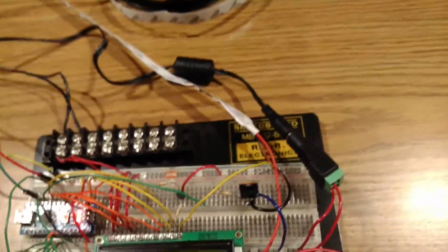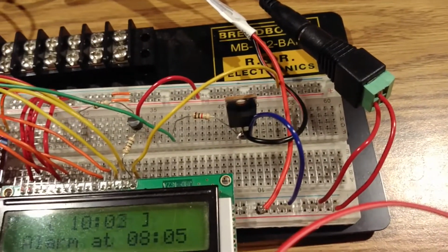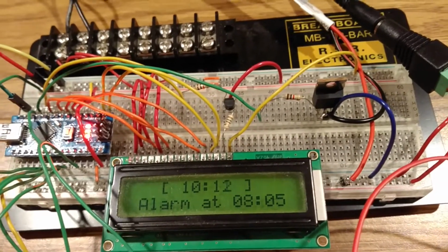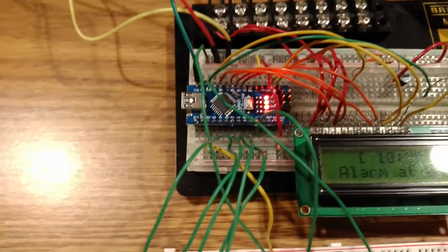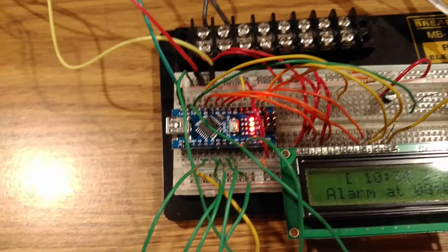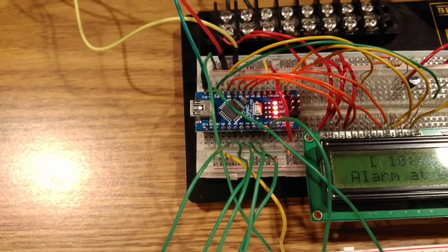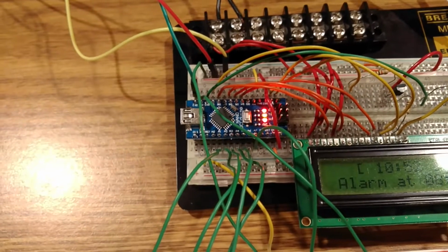For the LED strip, I actually had to power that off of 12 volts. So I needed something a little more substantial using that MOSFET there. And in order to PWM that, the LCD is fairly low current LEDs, so that I could use the transistor for. And then finally, the brains of the whole operation, the Arduino Nano that I used, controls everything here. So surprisingly, I was actually having spare pins. There's about 3 or 4 extra pins even with this tiny microprocessor, which I thought was pretty cool to be able to do with such a small module. But everything is controlled by that Arduino Nano.